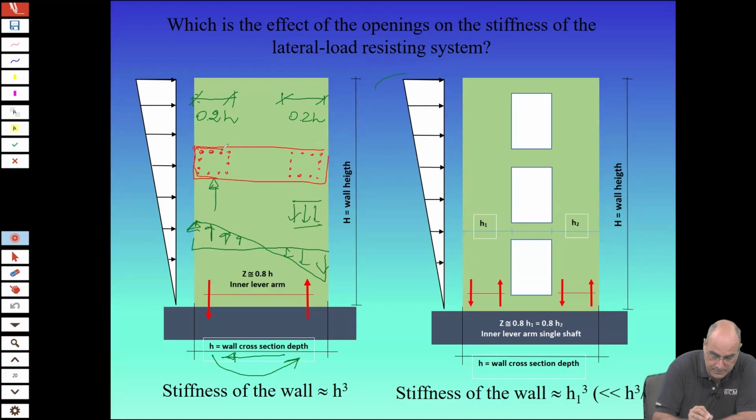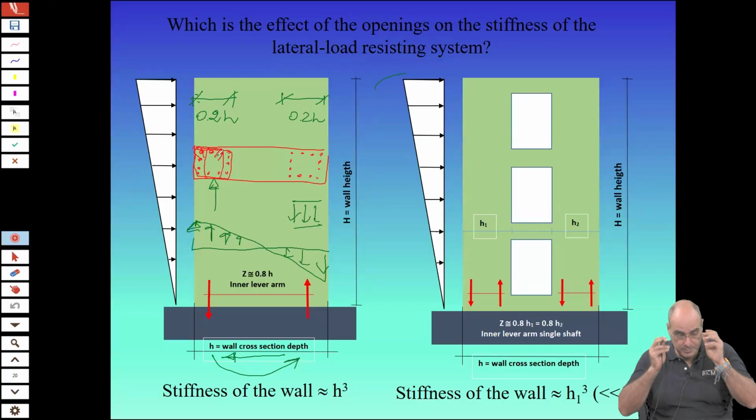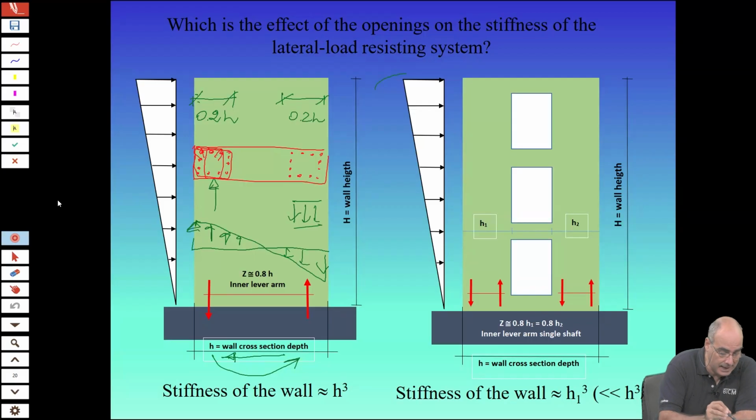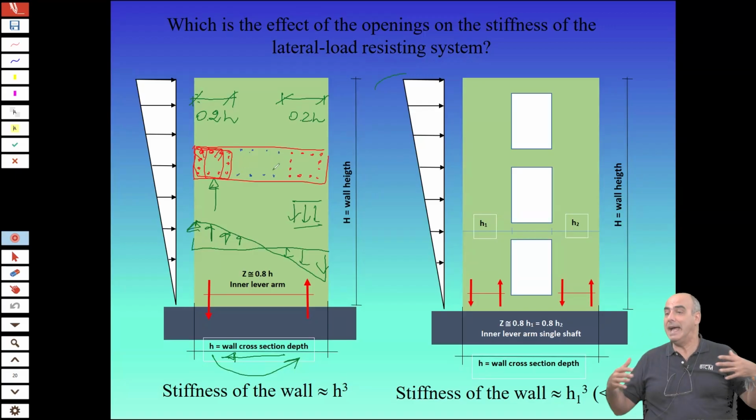And here you will have some stirrups as well, or probably even something like this, always closed stirrups. Well, it's not that in the other part of the wall you do not have reinforcement. You will also have some reinforcement here, but less dense, more loosely spaced.